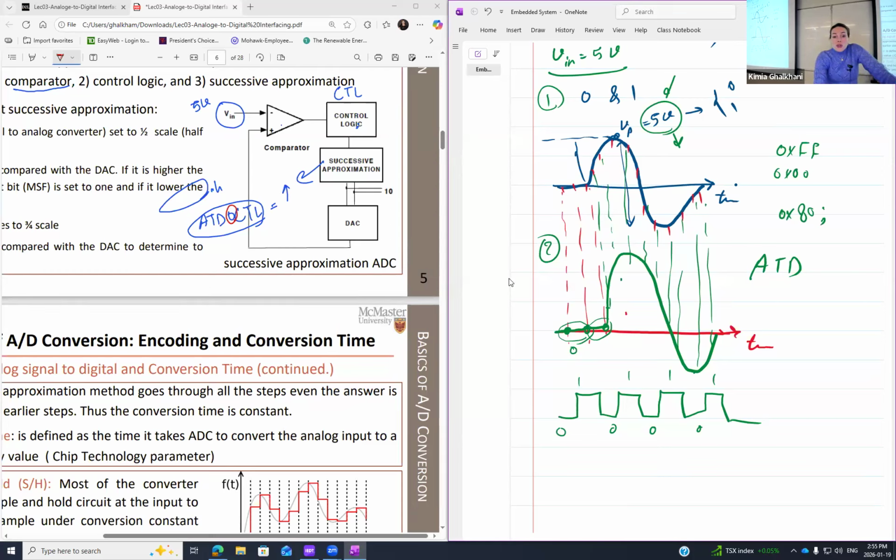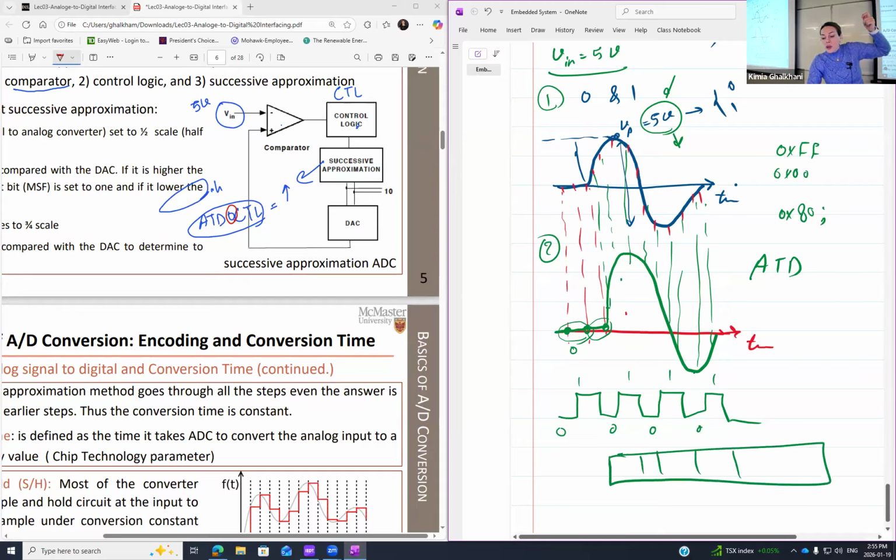That's what the control logic is doing. Control logic is turning on the entire analog, actually with only one bit, bit 7. If you turn on bit 7, remember it was an 8-bit register like this. I'm trying to quickly review. 1, 2, 3, 4, 5, 6, 7. So that one is 7, that one is 0. Remember I said if you turn this bit to 1 and keep the rest as it is, it's going to power up the system or the register. That's what we did in there.